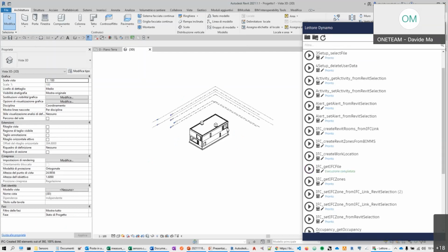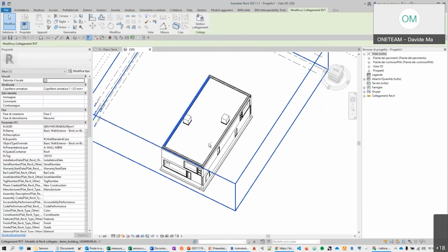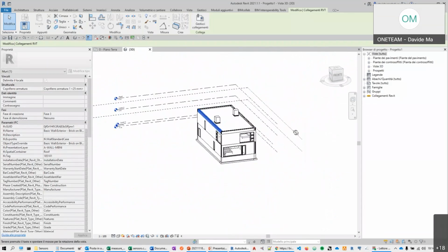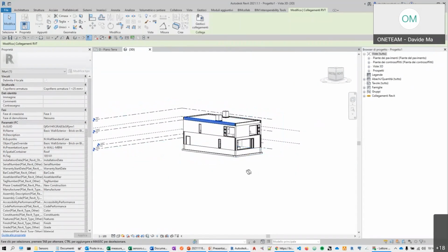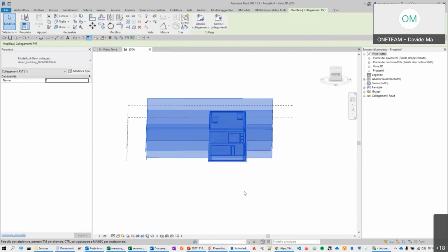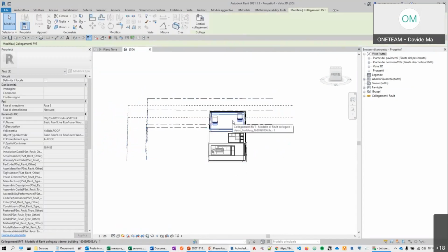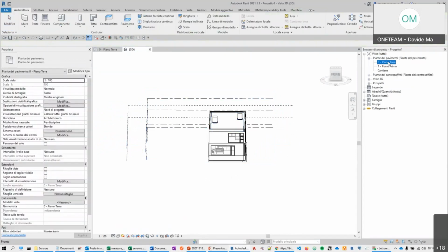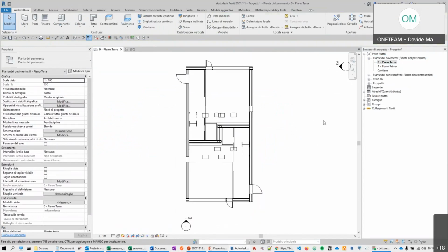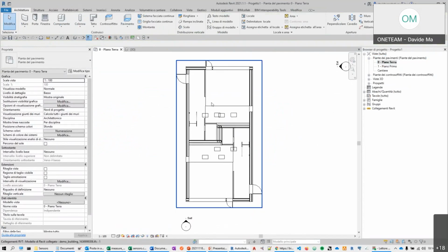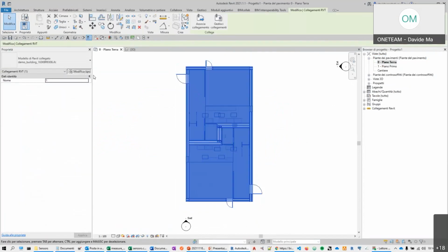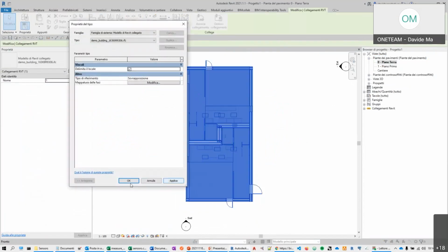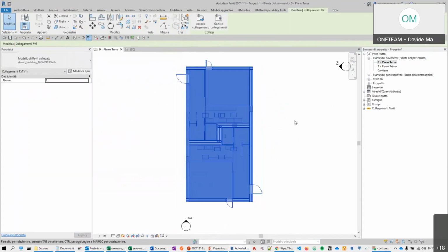It's not a file created in Revit, but you can work with it. This is the same file as before, but now it is directly downloaded and connected as a link in Revit. You can select the items as in any IFC file. And if I go to the floor plans, I can select the system, and I use that to make boundaries.